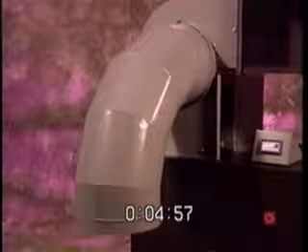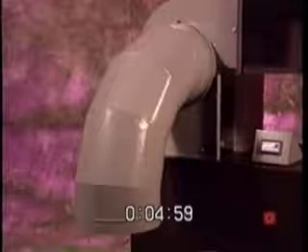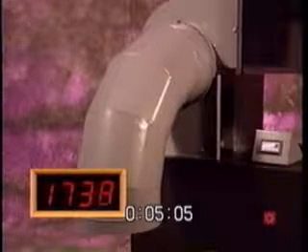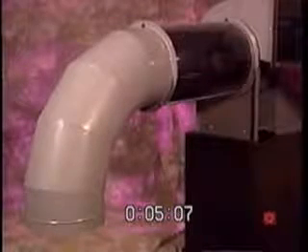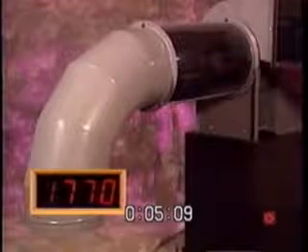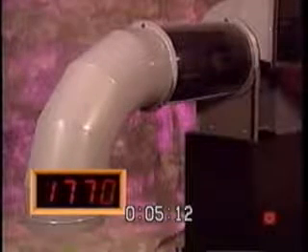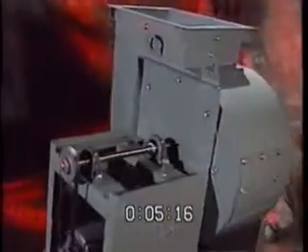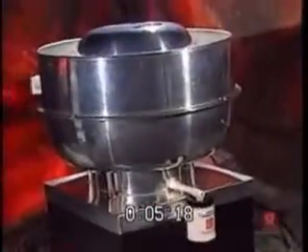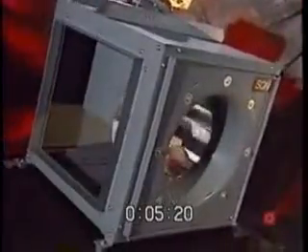A sweeping radius elbow at the inlet provides a more efficient solution. In this case, the airflow has been reduced around 3%. By inserting a straight section of duct, the airflow is now just 2% below the fan's catalog performance. In summary, proper fan selection and performance can be achieved if calculated duct losses as well as system effect factors are considered during the design stage.